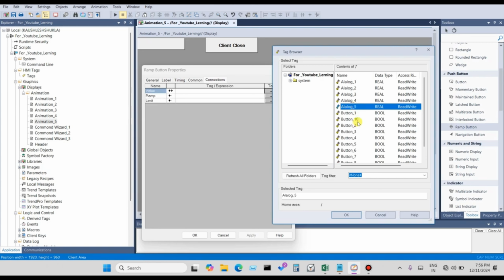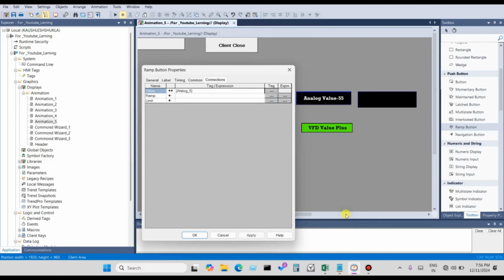Explain when I create this button in the faceplate of the pop-up. So at that time, I will put this button in the motor faceplate. For BFD, the motor faceplate will include one BFD faceplate. Click OK, apply, and okay. Next.